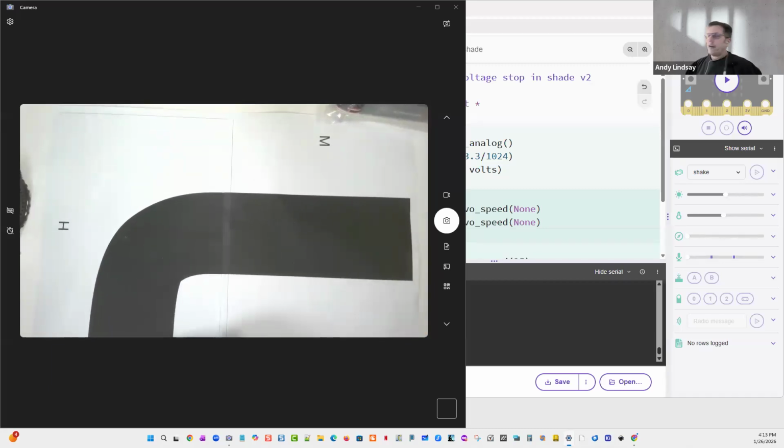It turns out that with color printers, the sensor is going to be shining infrared on this and then checking for a reflection, and it'll reflect off the paper but not off the toner black. Now if we instead use color printer black, sometimes the pigment that looks black is highly reflective of infrared, and so it turns out to not be detectable. That's why I put a little note in there about using a laser printer as opposed to a color printer.